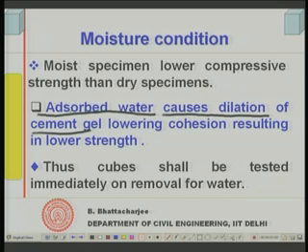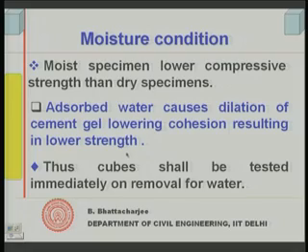But the fact remains that the moist cube shows lower strength. So, this also needs to be standardized, and therefore the code tells you that it should be tested on removal from water. Immediately after removal from water, you should test this, as quickly as possible. So, I think these are the test factors.